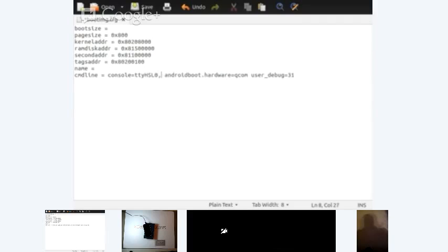And we want to set the parameters on that 115200 bits per second, no parity, 8 bits per byte. And now we want to make log level equals 9, which should show every single bit of output from the device. And I have no idea what this user debug equals. Well, let's go ahead and close this out. And I'll go back to this terminal over here.